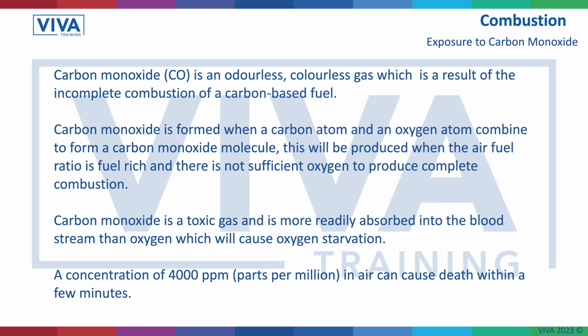What it does is like oxygen starvation. You're not getting enough oxygen into your blood. So one of the symptoms is yawning. Oh dear, your body's trying to compensate for the lack of oxygen by you yawning and dragging air in there. 4,000 parts per million in air could cause death within a few minutes. So obviously we've got to be aware of these things and make sure appliances are burning correctly.